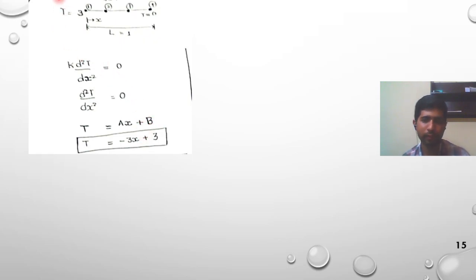We have already done the first step here. We have done the domain selection, we have done the grid generation. It's a 1D grid. I'm using the finite difference method. I have generated 4 grid points, and in those 4 grid points, 2 are boundary grid points. So I need to find the temperature at only 2 grid points here, which are marked as 2 and 3. If it's not clear, this is 1 2 3 4. So I have to find the temperature at the second grid point and the third grid point. I know the temperature at the first grid point and the fourth grid point.